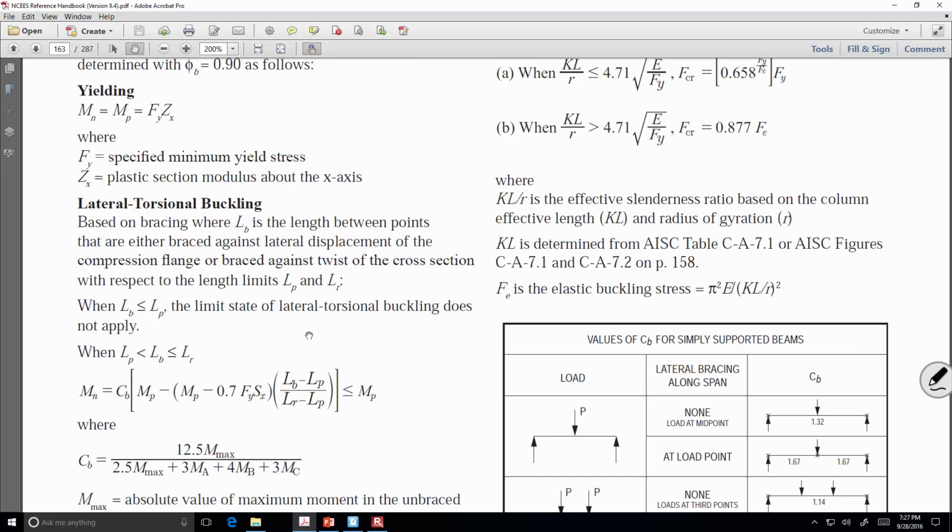It's all right here. When you have a beam, just like a column, the longer it gets, the weaker it gets. I mean, if you have a really, really long column, it's going to be pretty easy to buckle it. If that column's really short, not so much, right? Well, just like a beam, the longer it gets, the weaker it is, specifically its unbraced length.